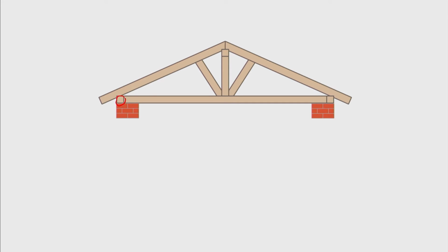The support to the left is assumed to be a fixed joint, and the support to the right is movable. From the assumptions made for calculation of plane trusses, the joints are assumed to be hinged. The load on the truss exerted by the covering roof is transmitted through the beams abutting upon the joints of the truss, so the load is deemed to be concentrated forces.